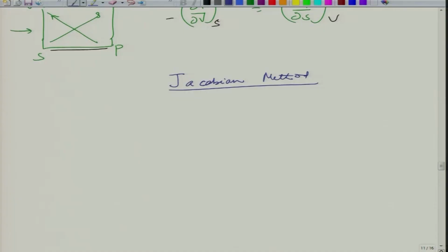Okay, welcome back. So let us start with the Jacobian method. This will be quite a simple approach in order to remember the Maxwell relations, as well as to apply them to obtain various different thermodynamic relations. So the efficacy of such a method, compared with one based on just derivatives. So let us consider x is equal to x(A, B) and y is equal to y(A, B).